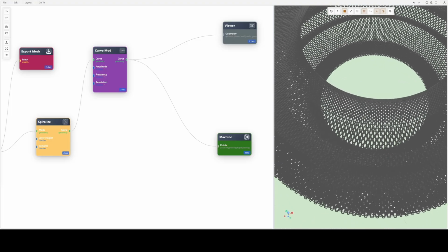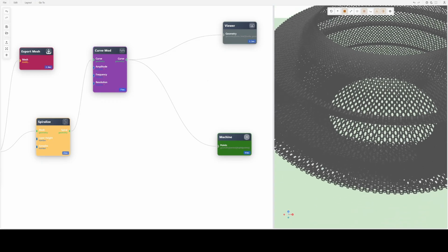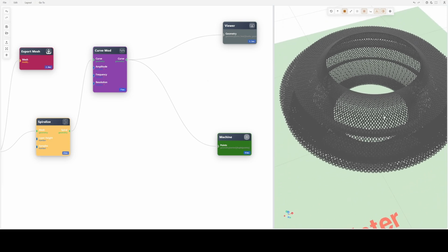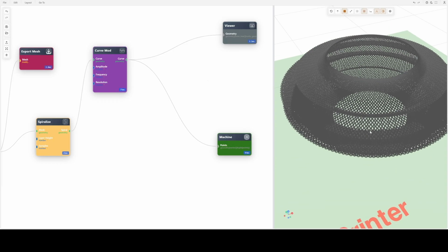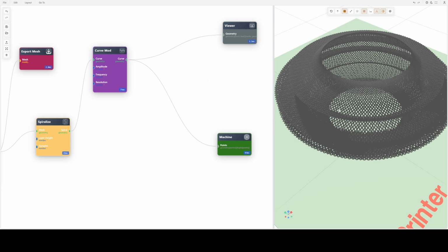You see it's not a normal STL mesh which you can slice, because you have this pattern here. Normally you can only print it with directly generated G-code, or what is often called custom G-code, because you need these variations in the toolpath, which normal slicers do not produce. But this is achieved in one of the later stages of the design.